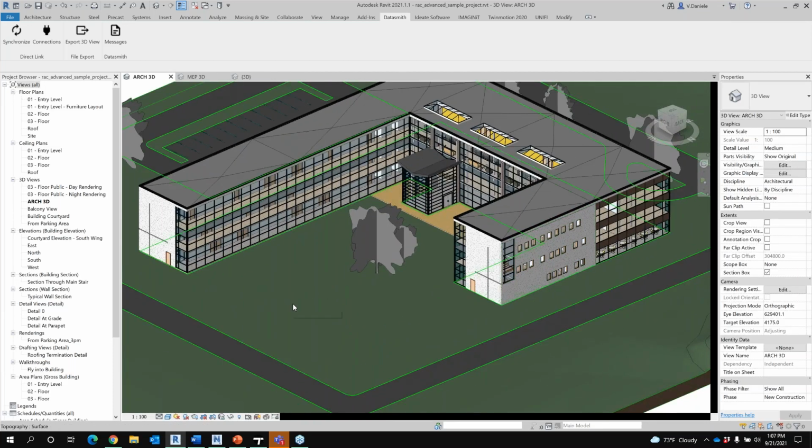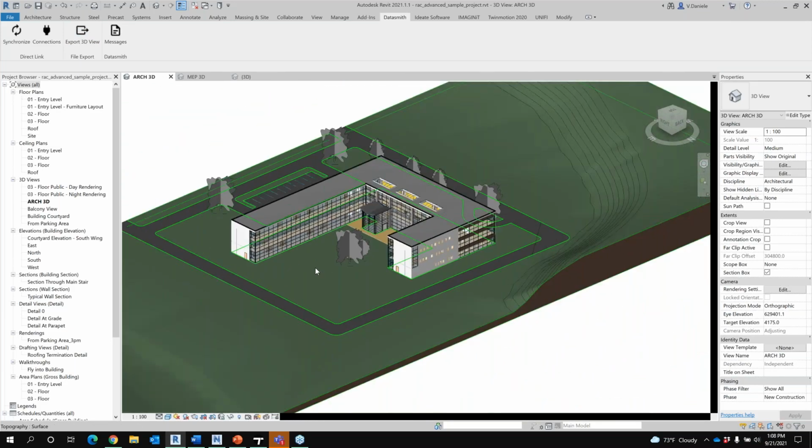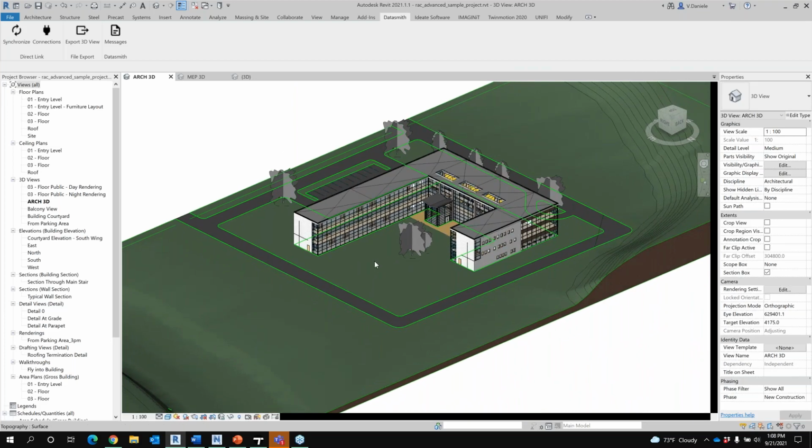So anyways, to explain the whole idea behind taking our Revit models and bringing them into Twinmotion using the export function, really what you see is what you get on your screen. So if you're in a 3D view, and you do have to be in some form of a 3D view when you go to export to a Datasmith, and you have certain Revit categories isolated or certain categories turned off, when you do go to export your 3D view, it will simply ignore the objects that are turned off and it won't package them up in the Datasmith. So that's kind of powerful in itself.